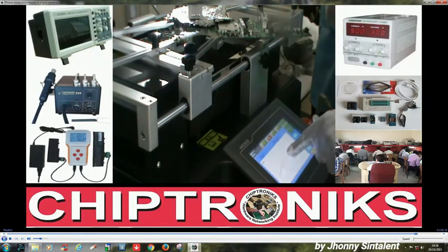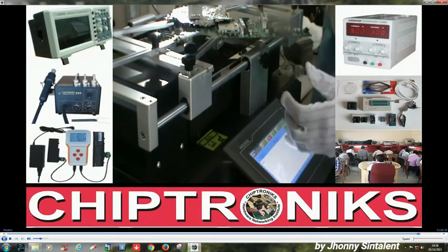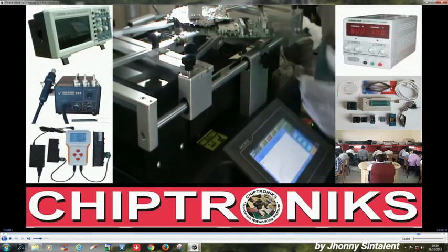So you can see there is a ramp of temperature. The lower heater temperature is higher than the upper heater, while the top and bottom heaters are close. The heaters which participate in this work are mostly the top heater and the bottom heater, while the side heater is for maintaining equilibrium on the board. You know, PCB equilibrium. If you do not heat, then it will get bent.